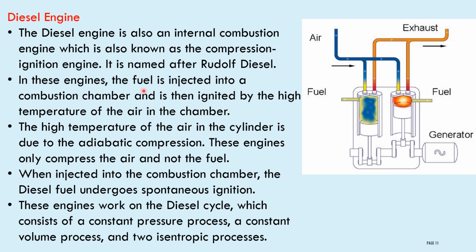In this engine, the fuel is injected into a combustion chamber and then ignited by the high temperature of the air in the chamber. The chamber already contains air at high temperature. When the fuel enters the chamber and contacts the air at higher temperature, it is immediately ignited. The high temperature of the air in the cylinder is due to adiabatic compression.